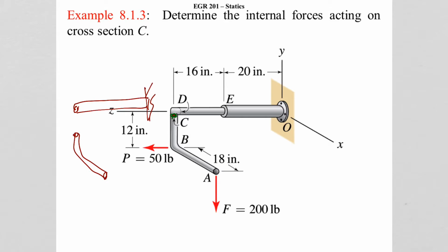Well, to make life easier for us, if I look at just this section here, I don't have to worry and solve for our reaction forces at O. So I'm going to draw the free body diagram of this lower section so I don't have to calculate all of those moments and forces in the X, Y, and Z direction at O. Sometimes you may have to do that, though.